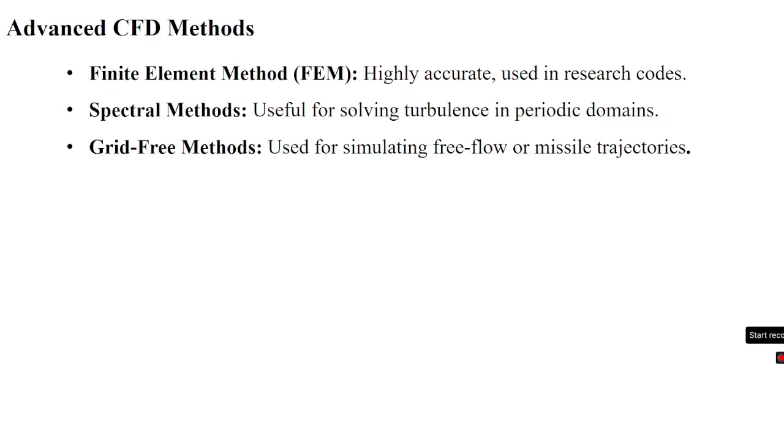So what is the advantage of finite difference method? It is simple to implement, especially for simple problems like conduction and convection, and can be used to calculate higher order derivatives by incorporating more points. But it has some disadvantages. It doesn't work well with complex geometry like airfoil shape, having different shapes. As it requires structured grids, it is hard to apply to non-rectangular or irregular domains.